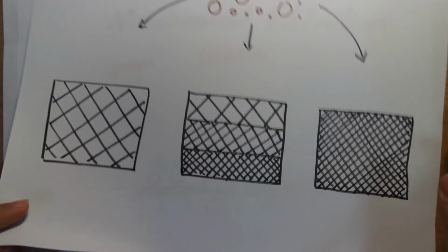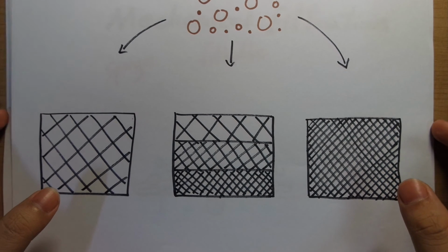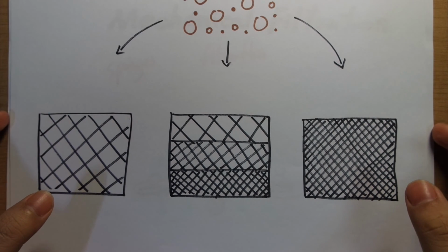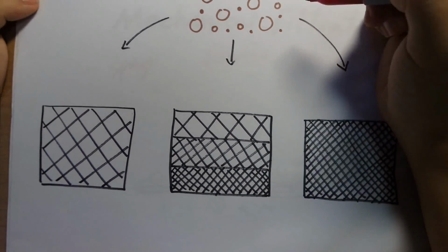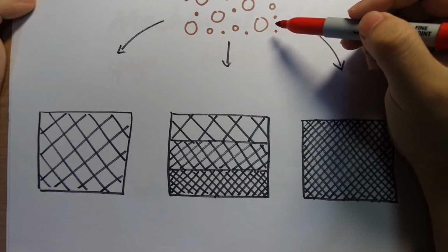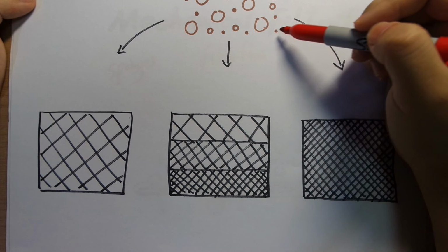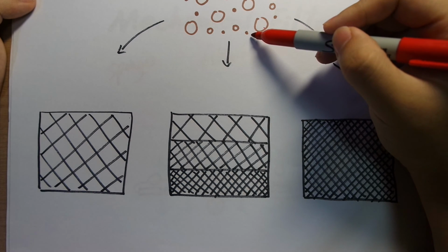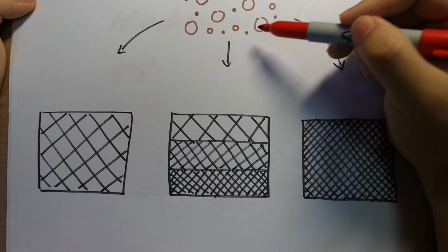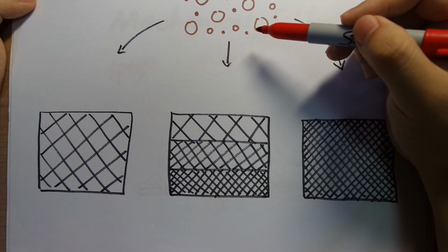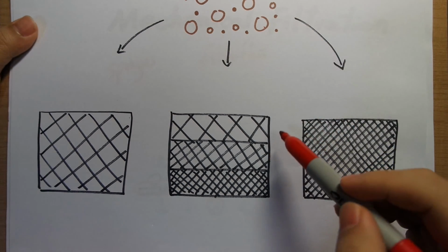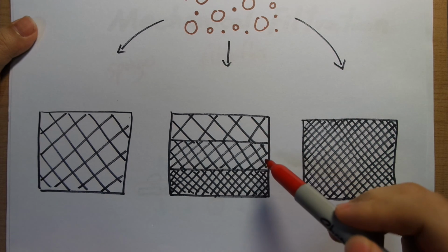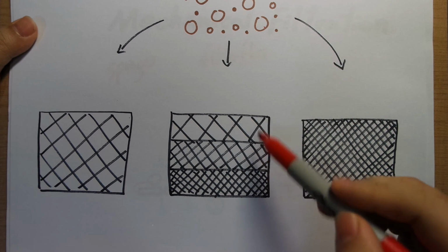How you layer mechanical filtration is a concept that a lot of people seem to confuse, so I'll be discussing that here. Basically, in your water, you're going to have solids in a variety of different sizes. You're going to have some large ones, some medium ones, and some small ones. So you want to have several different layers of mechanical filtration to account for that. The ideal way to do that is to go from coarse to medium to fine. That is the way you want to layer that.